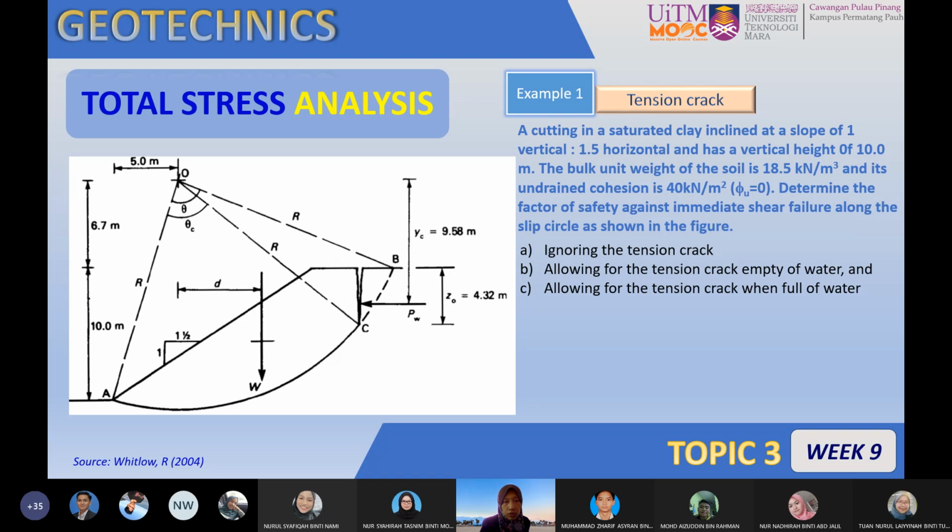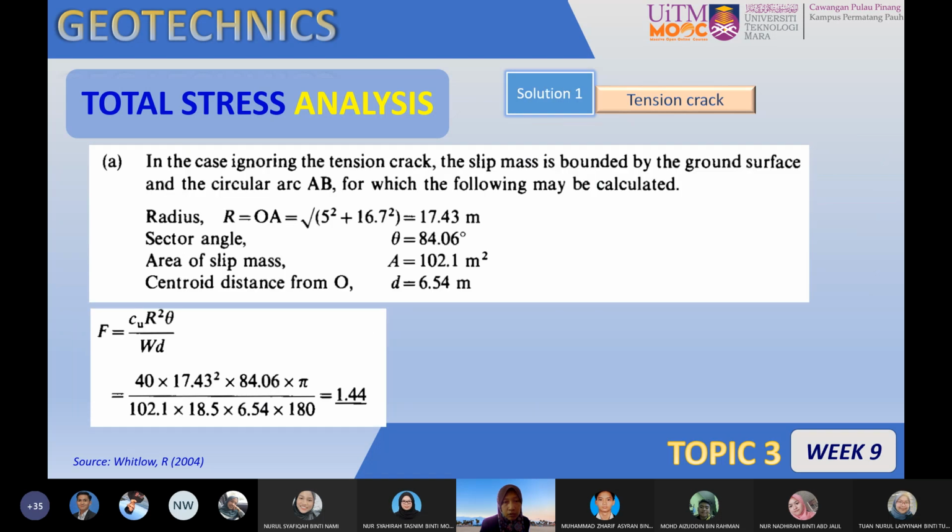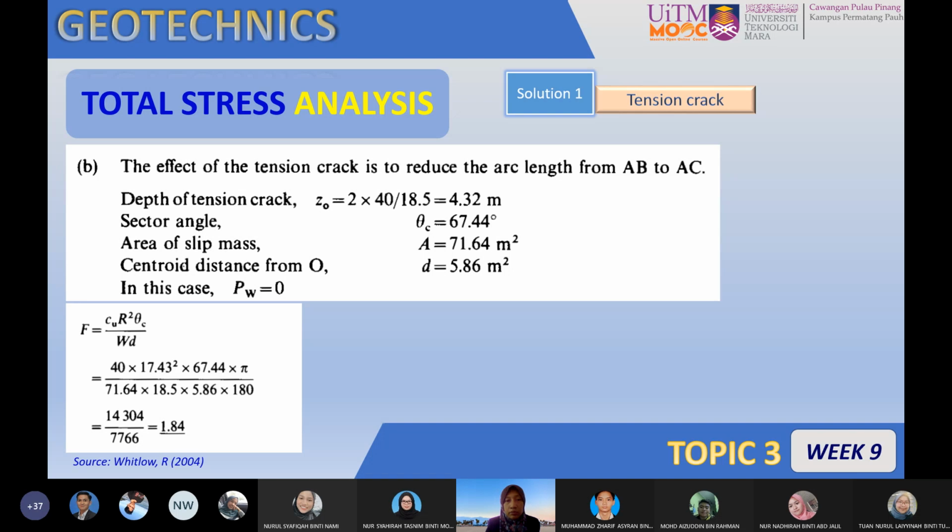It's very important to check closely the parameters involved, the right values to be considered in the calculations. And when you have all those parameters, you substitute into this formula. So first of all, we have the FOS is 1.44. Automatically, we can say that the slope is stable by checking that the FOS is 1.44. The FOS is unitless. Please make sure when you write down the answer, there's no unit next to the figure.